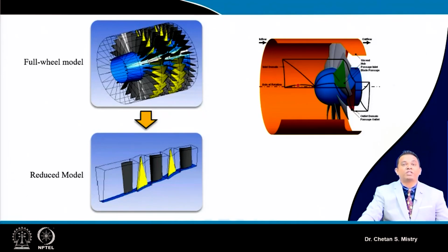Okay. Now once we are ready with our blade, when we are doing our CFD analysis, that blade we need to consider as a hollow portion, and the remaining portion, which is of our interest, will be solid. So just understand one thing here, this blade we are talking of is a hollow passage, and the remaining flow domain will be a solid passage, and that we will be dividing into a number of elements. So let's look at what we need to do here in terms of discretization.